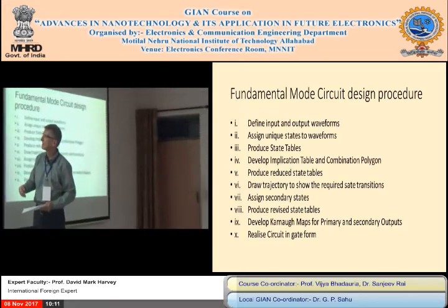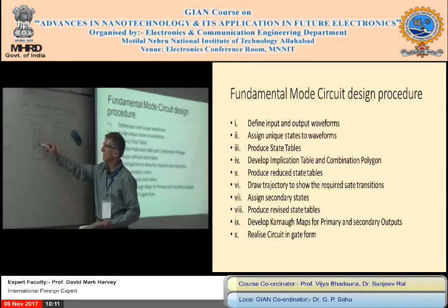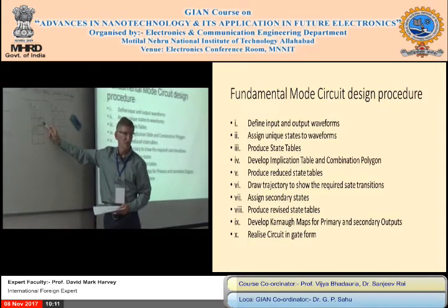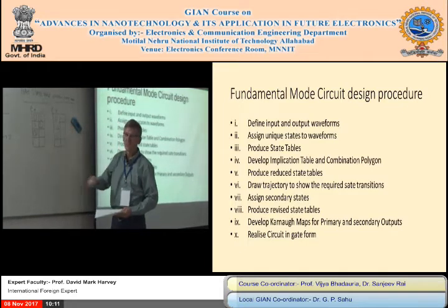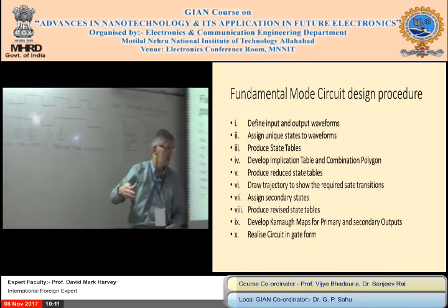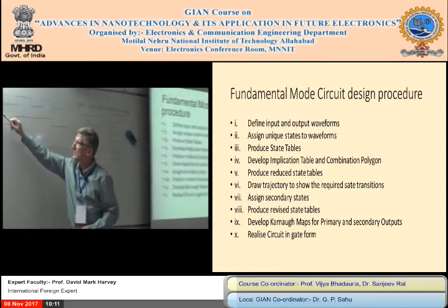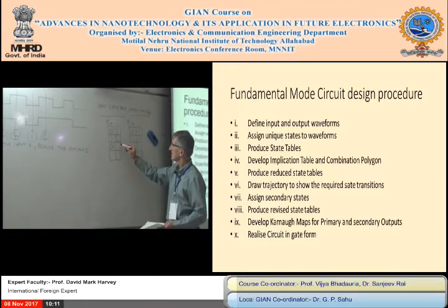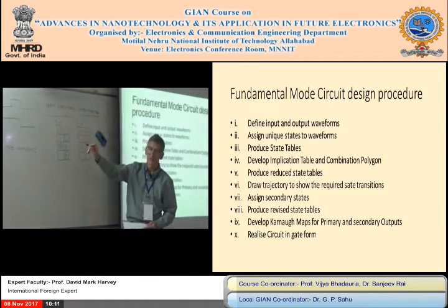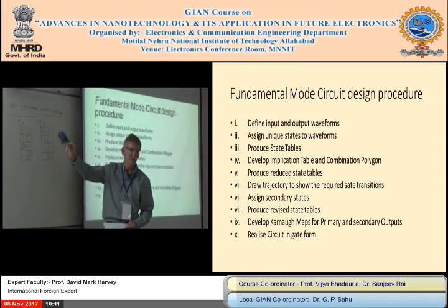Then the input goes from 1 back to 0. We're going into stable state 3, so we put a transition state 3 in there to point us where to go. This time both the stable states have a 1 on the output, so we make the transition state 1 to maintain the output. We don't want this output going anywhere when we change the level. And the next one, 3 to 4, we're now going on the input 0 to 1. So there's the transition state 4 to tell us where we're going. Both stable states are 1, so we'll make the transition state 1 to keep the output high.